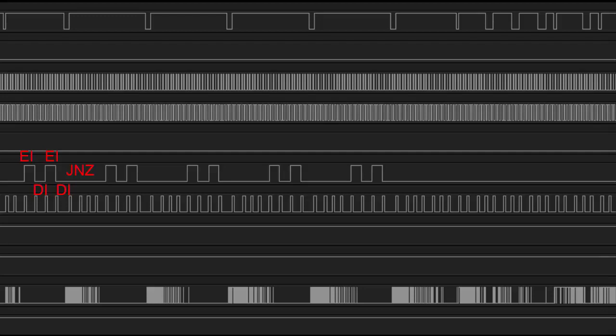So what this tells me is that the instructions the 8080 is getting off of the bus, out of this memory chip, are valid instructions. It's doing exactly what I told it to do. The first thing I tell it to do after it comes out of a reset at instruction 00 is to start toggling this interrupt line 5 times. Since I see that in the waveforms, I know that this 8080 is reading valid instructions.